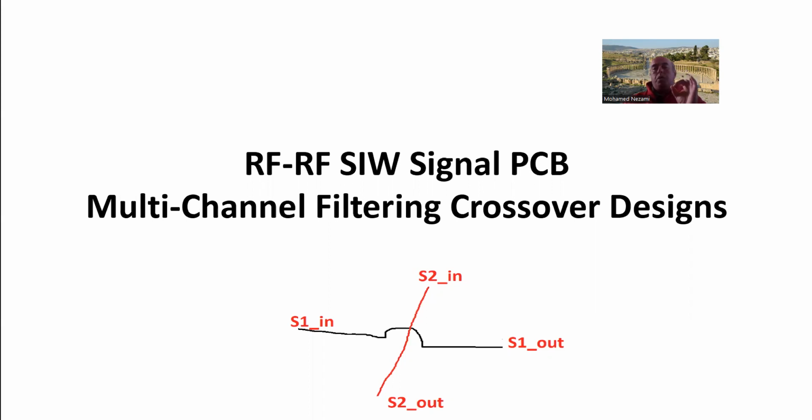So when people looked at this, they realized for a resonator with the SIW, if it's a square, then you can have two dual modes, where you can feed it on one side and get the other side, and then feed it orthogonally 90 degrees on the other side, and then get out on the other side. And they found out that these things can be totally isolated, and therefore you can have them as a multiplexer. If it's a square, it's the same frequency, whether you feed here or here, but they cross each other and they don't interfere; there is high isolation.